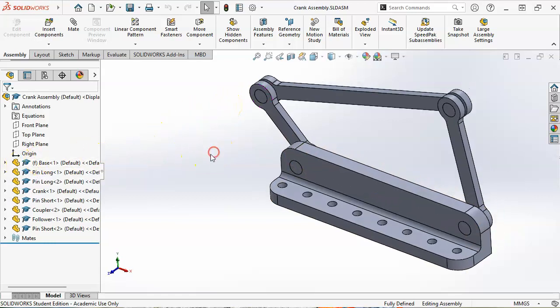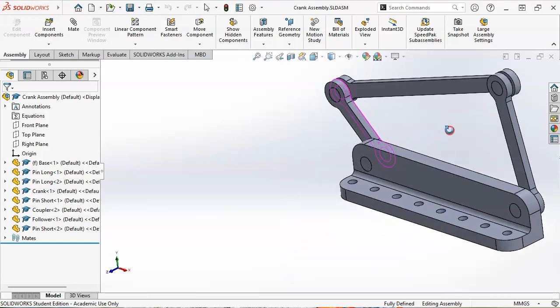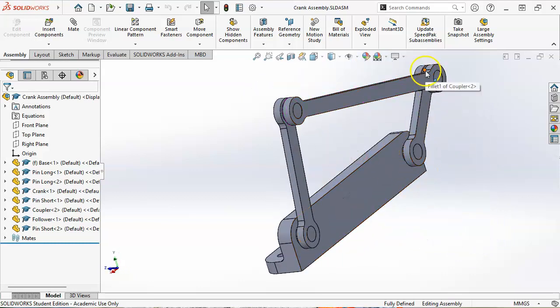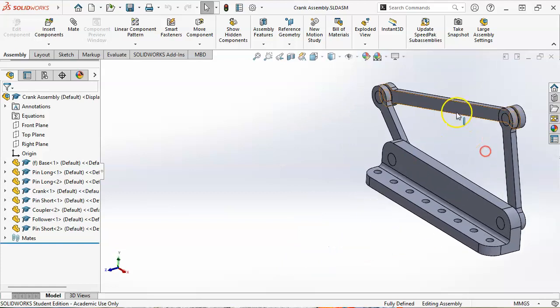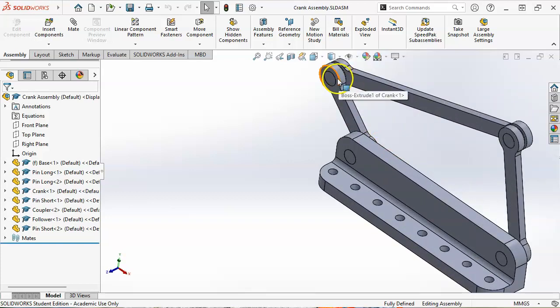All right, so one of the things we can do, and one of the reasons I wait to define, and I'm happy with my geometry, like I said, is if these are loose and one side goes light and the other side goes heavy, that would also affect that this is spinning, that's a press. Then looking at this, I need to go back and decide which one of these is going to be a clearance and which one's going to be the press, because on the drawing, if I'm going to press in on that side and have it remain stationary, then the other side's going to have to be clearance.